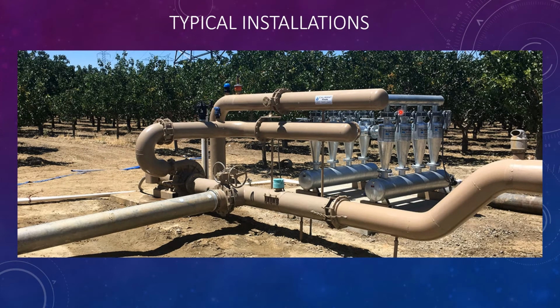Now, here is a recent installation, and these are all 2 or 3 inch hydrocyclones. Notice the diameter across here is quite large. This is galvanizing, so they're going to have rust and abrasion issues, and eventually these are going to fail, probably within about 5 years or less. And you'll also notice that they're not center fed, so now some of these separators are going to see more solids than others. But the bottom line is, I was doing this 20 years ago, and yet the market is just cottoning on to using smaller separators in lieu of one large one, as you'll see in the next slide.